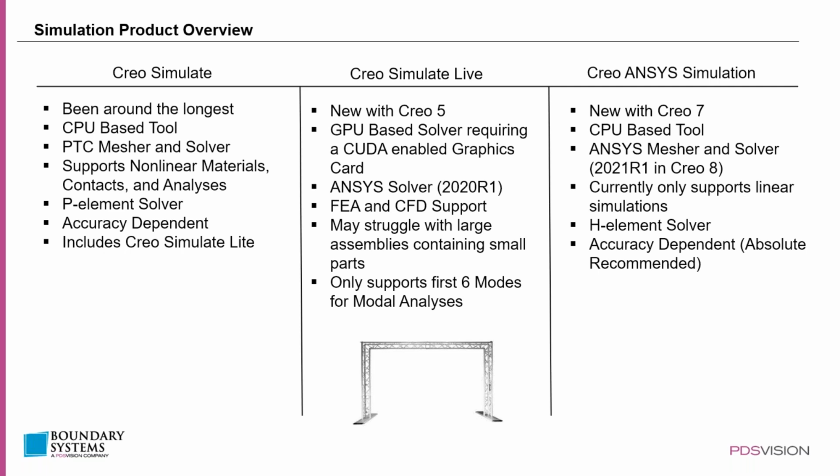If you're not sure, then you can find various lists online. One list from PTC of which graphics cards are supported, and additionally a tool that you can run on your computer that will tell you if your computer is able to run this. But that's just something to mention right away. It does have very steep hardware requirements.